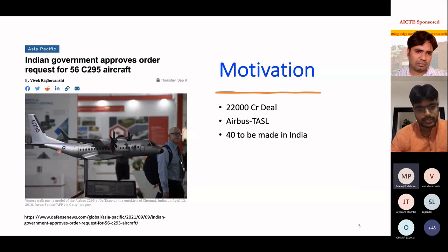So one thing to note here is that this upsweep is very, very high in the military cargo aircraft or in general cargo aircraft. And what is the reason behind that? Is that because the paratroopers need to jump, right? So they have to jump from here. So there's a cargo door located here that needs to open whenever it is needed. So when you need to open a door, this door will open like this, right? If it is very close, suppose upsweep is very less, it will basically go down against gravity and things might fall. So what they do is that they make it more upswept so that there is no difficulty in opening the cargo door. So that is a requirement from the military side or from the cargo side, and that leads to a very beautiful flow phenomena.